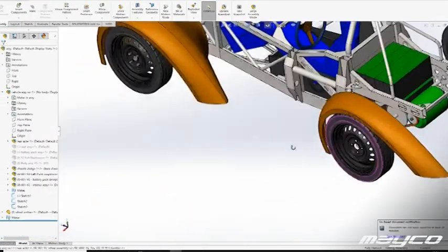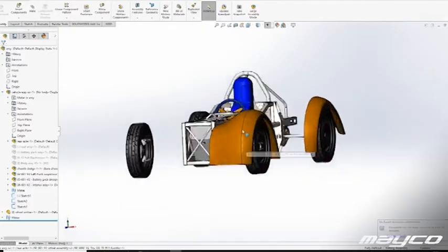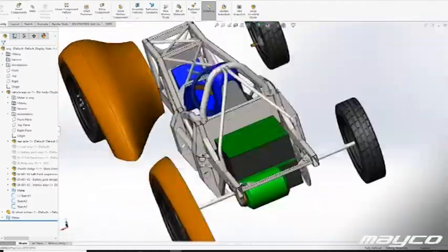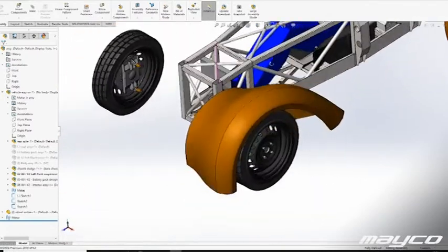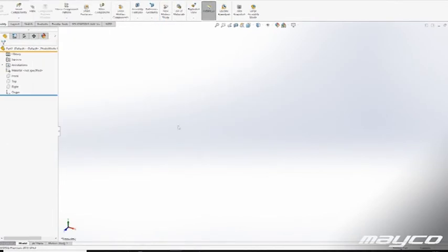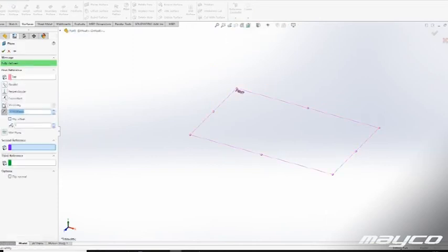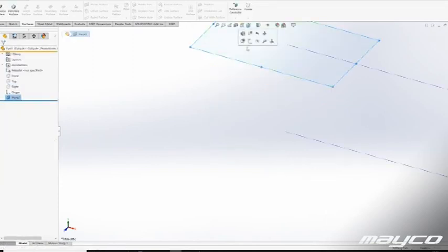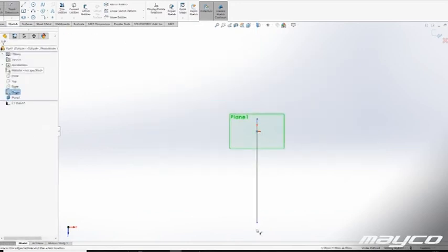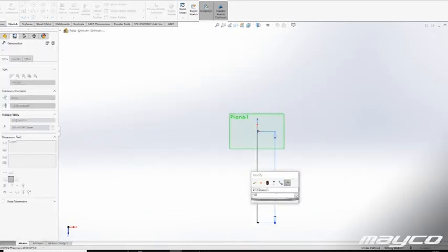Then the only thing that you can do is look if you can see something obvious. Second thing you can do is just click one or two surfaces that you think are very good, and try again to thicken those two, and then add some and try to thicken them again, and add another few, thicken them again, and as soon as you start hitting an issue, then that's most likely your issue. And sometimes it's very clear, and sometimes it's absolutely not.